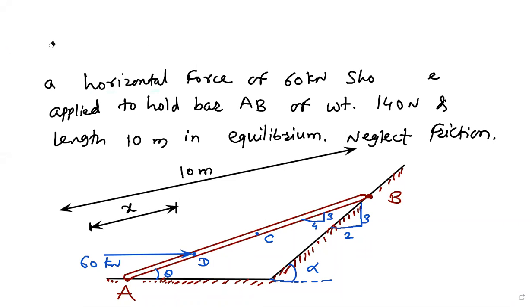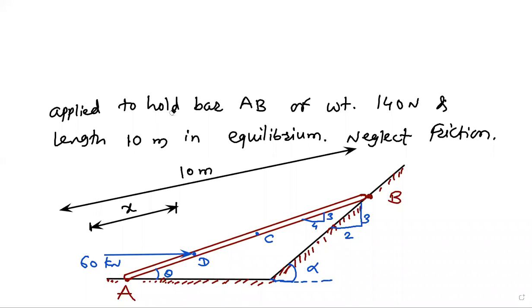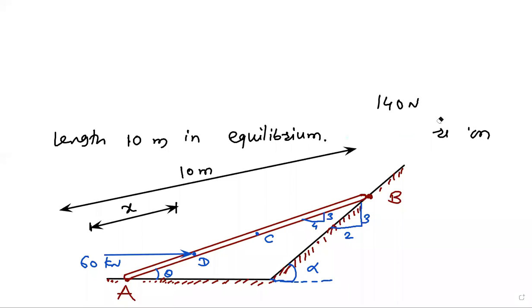Now first we will draw the free body diagram and show the reactions. Find out the angle. Then after that, we will use the equations of equilibrium. Remember, the weight of the bar is given as 140 Newton.